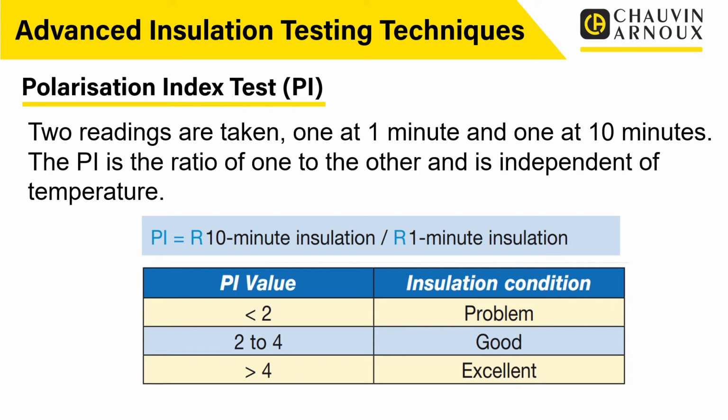So sometimes, like we said, for higher test voltages or for bigger installations, this may be a good idea to try. Again, you can do both. You could try a DAR test, and if you're not 100% convinced with that, go for a polarization index test. These aren't exclusive. You don't have to just pick one. You can carry out these tests and see the difference.